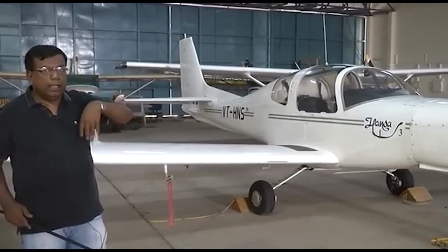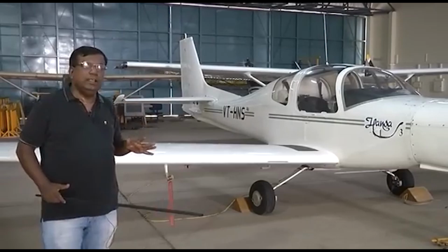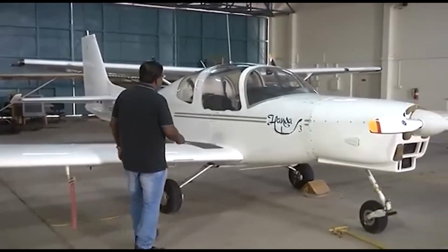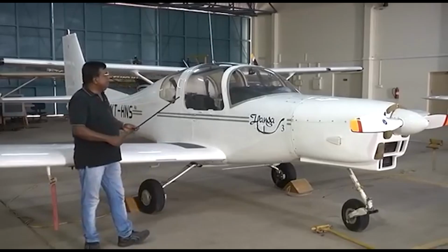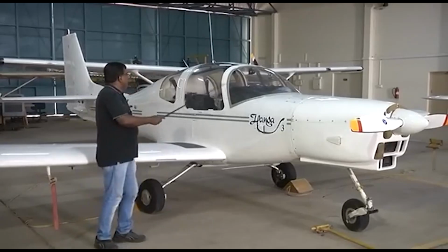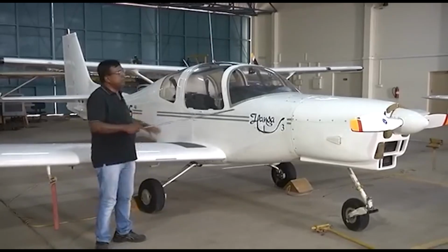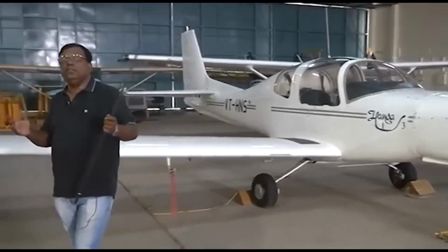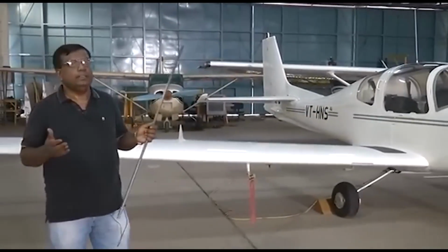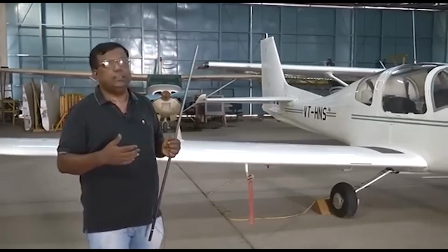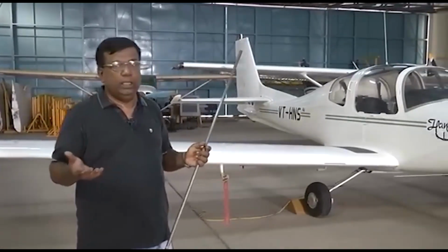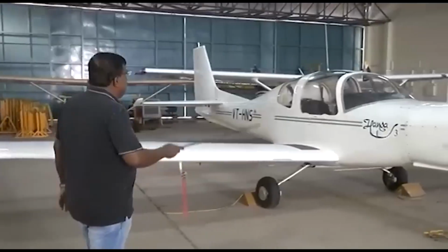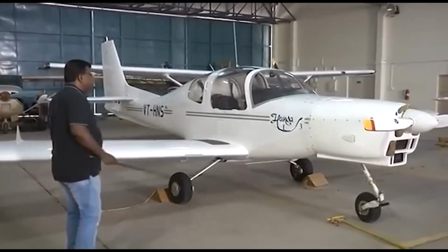So now, when I am analyzing the cruise, I am very clear that the whole mass of the aircraft is at the center of gravity, and the net force I have calculated by transferring them from different components. Then I am resolving those forces and finding accelerations. And if it is a non-accelerated or unaccelerated flight, I am putting that as 0 and going step by step, whatever is required. Right? So that is what is typically the point mass model.